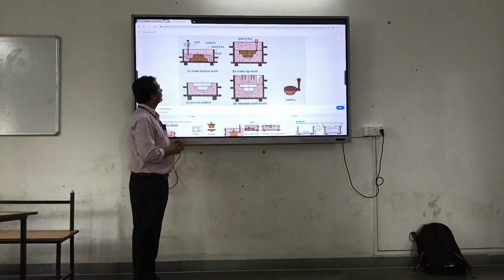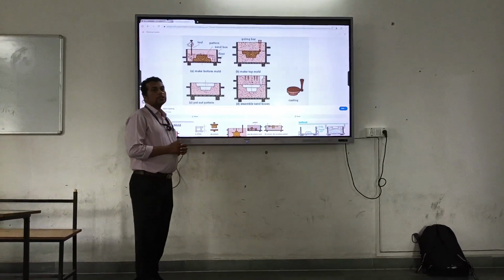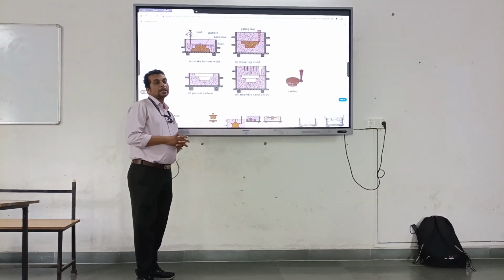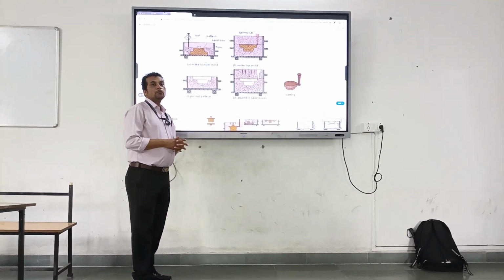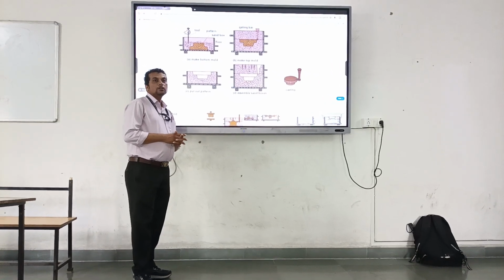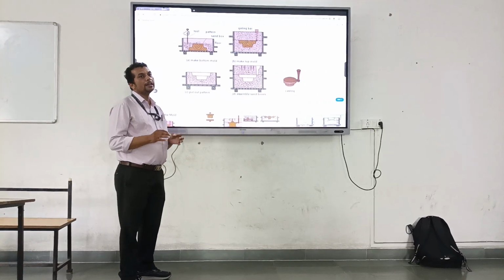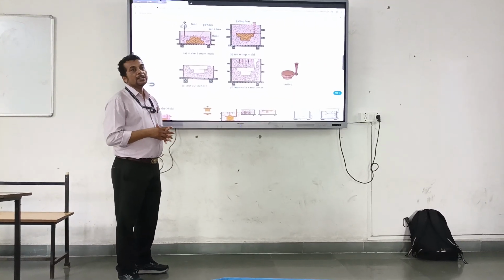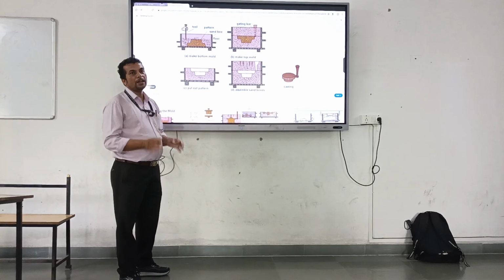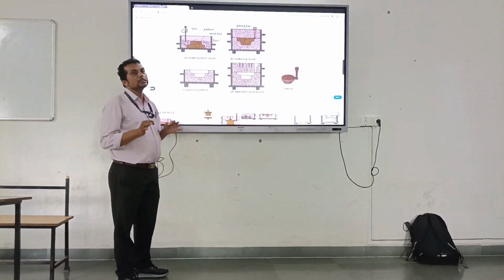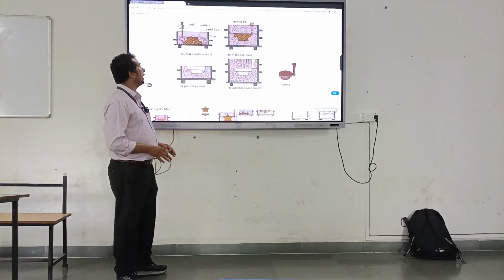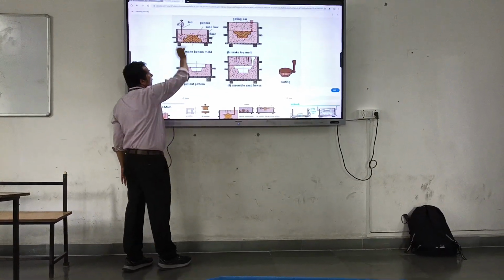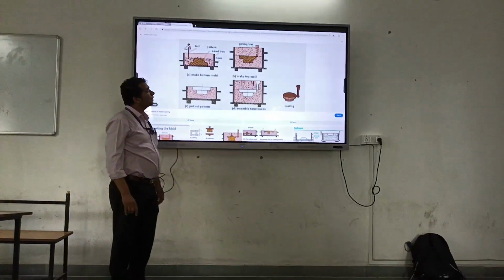After that, some quantity of mixed sand is required as fine sand, so riddling is required. After riddling, we will get very fine mixed sand. This fine sand we can pour over this master pattern.